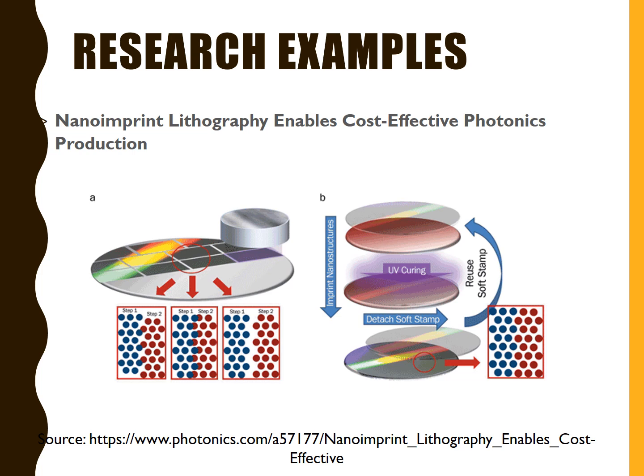So nanoimprint lithography bridges the gap between research and development departments and high volume manufacturing. NIL is the best suited lithography technique that can adapt to the needs of the photonics industry. The full-field ultraviolet version of nanoimprint lithography can print patterns on large areas without stitching errors and supports a gamut of structure sizes and shapes, which is a critical to quality criterion for many photonics devices.